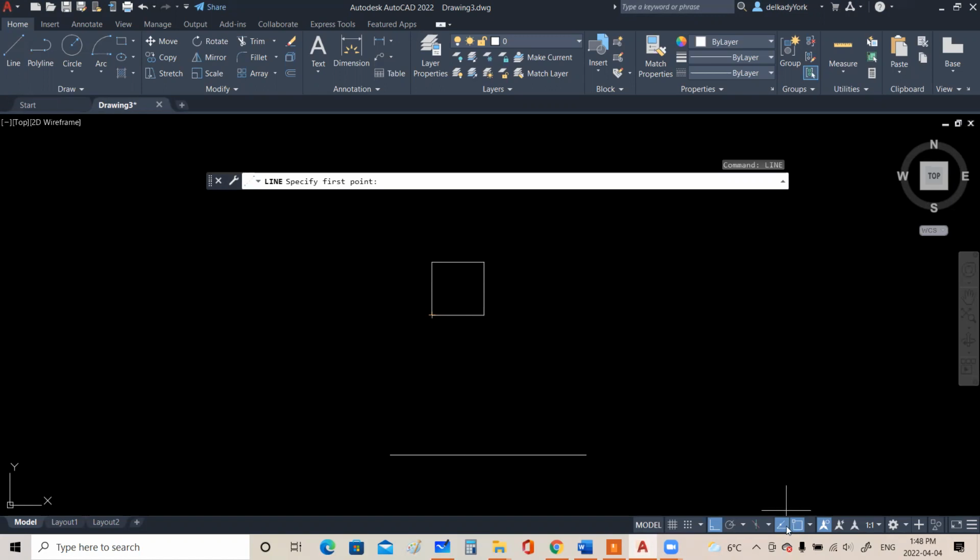So those two have to be working together while ortho is active as well. If I hover over this point, I'm not clicking, I'm just hovering. Whenever you hover over it again, that plus sign is going to be deactivated, and when you hover again, it's going to be activated. And then I'm just hovering till I get to that line.